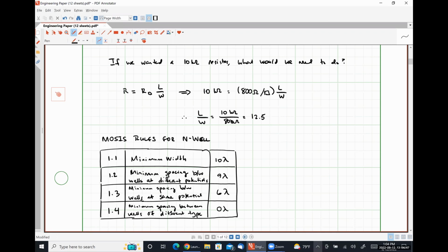And for an analog integrated circuit where so many different things depend on specific resistor ratios, you need to be able to guarantee that the resistors maybe aren't necessarily a specific size, but have a specific value as compared to something else, so that your voltage divider circuits and things like that that you're using for biasing will work and properly bias your electronics. Okay. It just comes down to simple mechanical limitation. Pretty much, yeah.